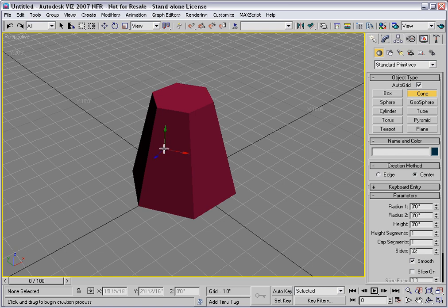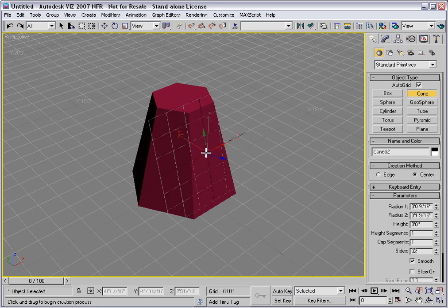The z-axis of the tripod is parallel to the surface normal, pointing away from the surface. The xy plane of the tripod is flush with the surface. The xy plane is the creation plane, so this makes it easy to create an object that's flush with the surface that you're hovering over.